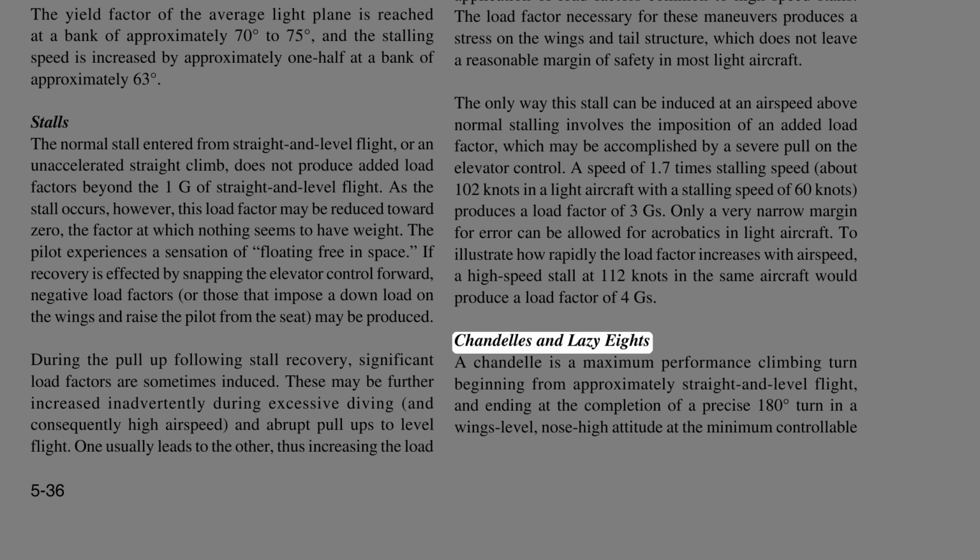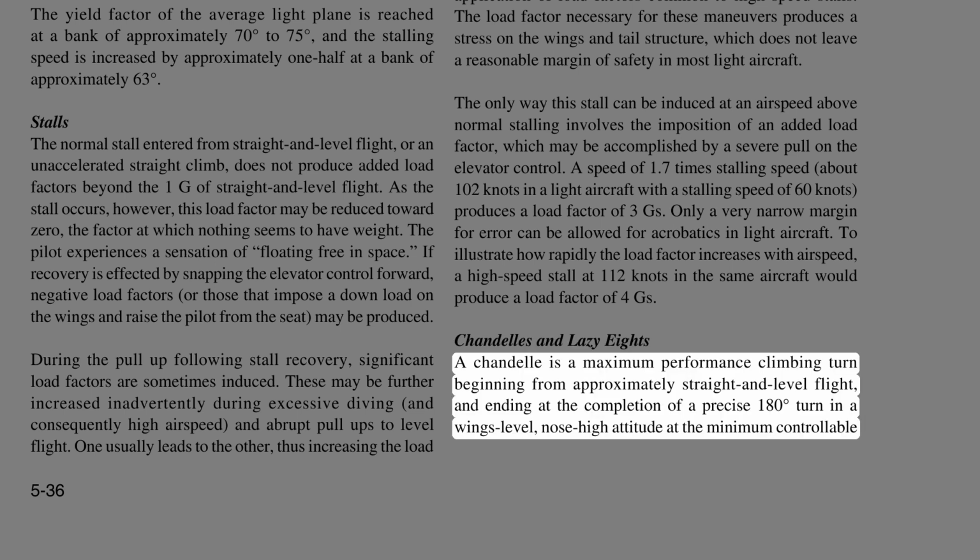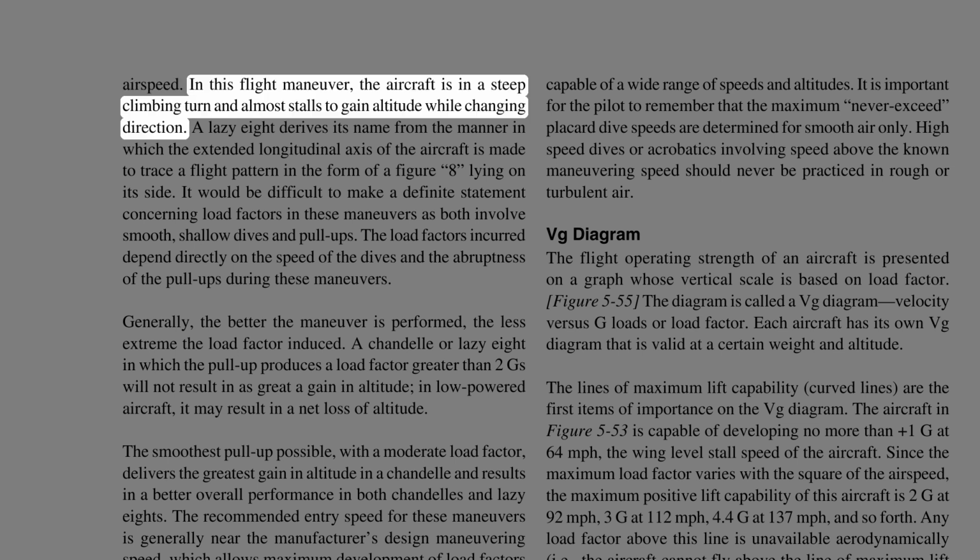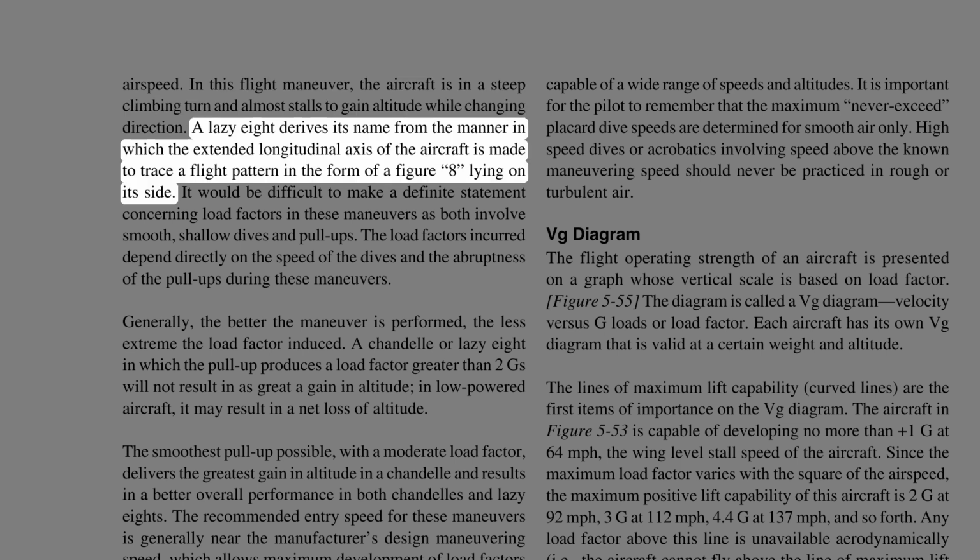Chandelles and lazy eights. A chandelle is a maximum performance climbing turn beginning from approximately straight and level flight, and ending at the completion of a precise 180 degrees turn in a wings level, nose high attitude at the minimum controllable airspeed. In this flight maneuver, the aircraft is in a steep climbing turn and almost stalls to gain altitude while changing direction. A lazy eight derives its name from the manner in which the extended longitudinal axis of the aircraft is made to trace a flight pattern in the form of a figure 8, lying on its side.